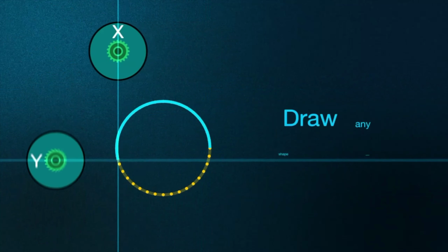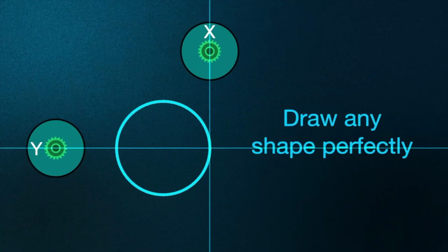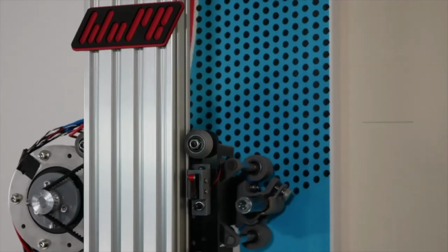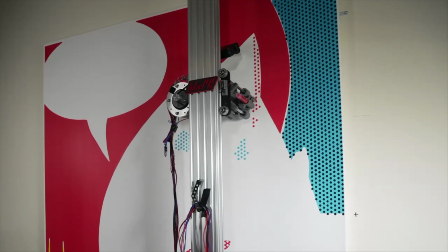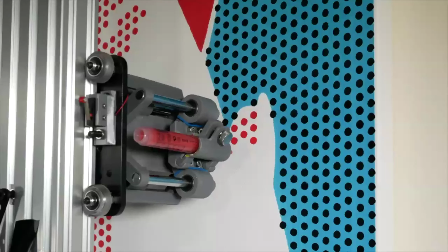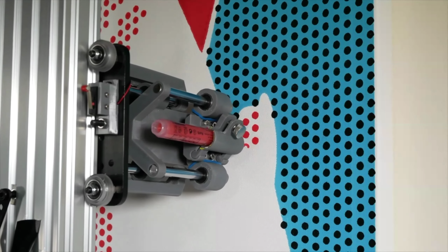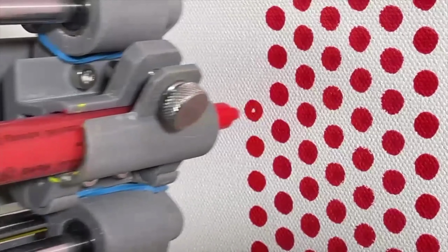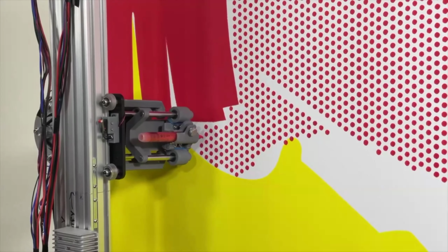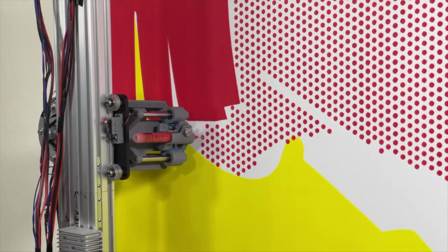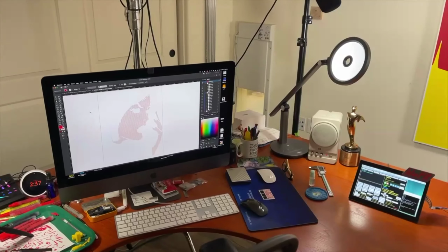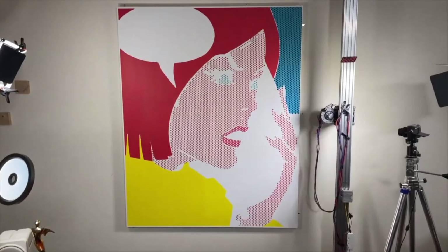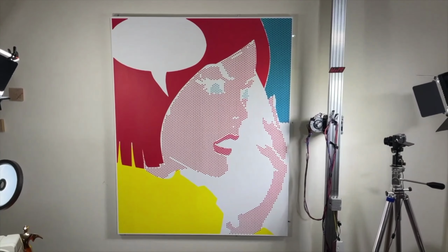So if suddenly either Xojo or the Pi decide to check the UI, wait for input, or give a CPU time slice to another app, the change your speed command wouldn't be given in time, or maybe not at all, and the printhead would just keep going, possibly until it hit the side of the frame. But the answer to that was to do tight loops. And when I'm in those, the user interface freezes while my loop is drawing the shape. Without the ability to do that, I wouldn't have been able to use the Pi for this project.